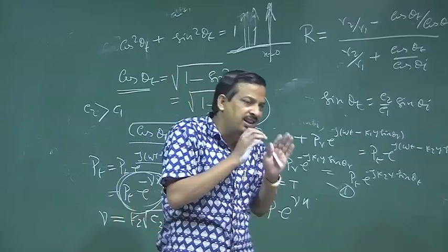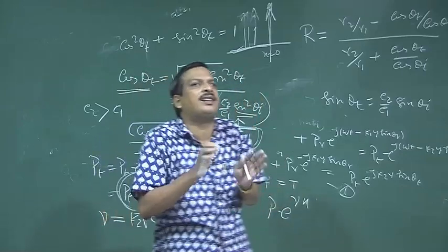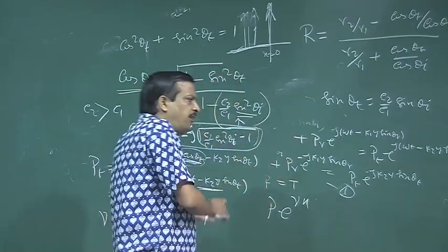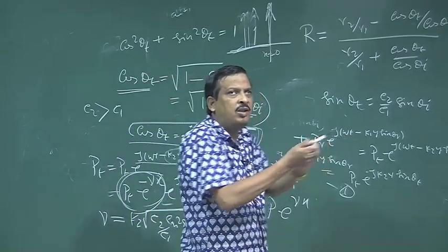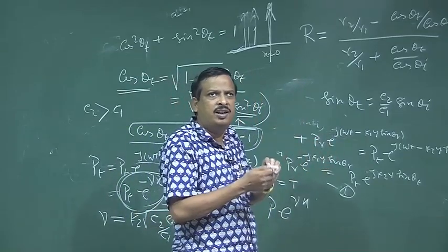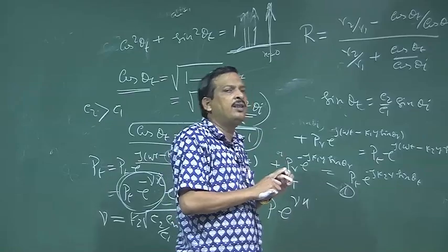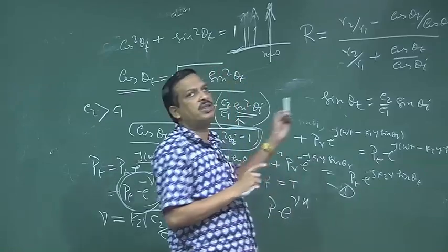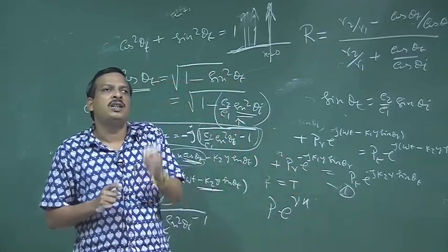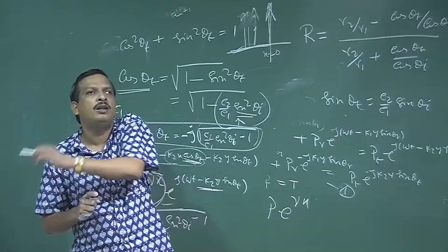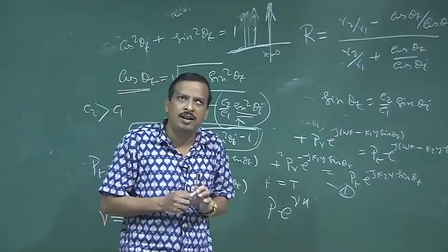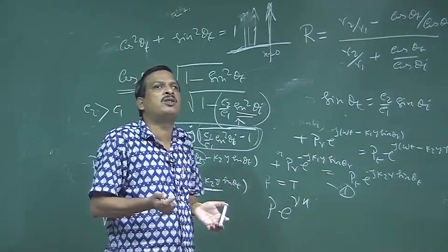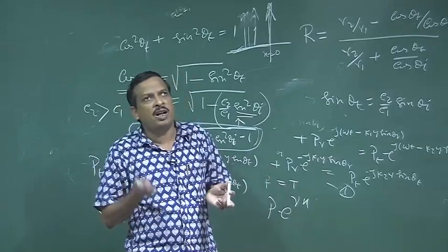Okay. So, that is the oblique incidence case. For normal incidence, that means the wave is propagated along the x direction only, y direction is 0 because it is normal incidence. For normal incidence we have derived that the pressure transmission coefficient is inversely proportional to L, and the intensity transmission coefficient is inversely proportional to L square.